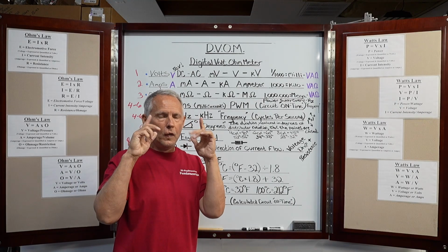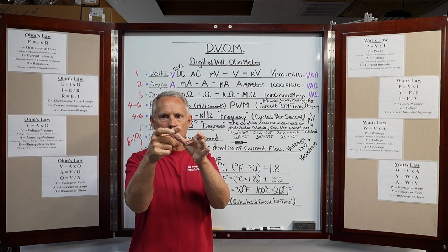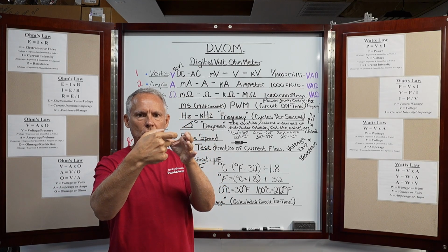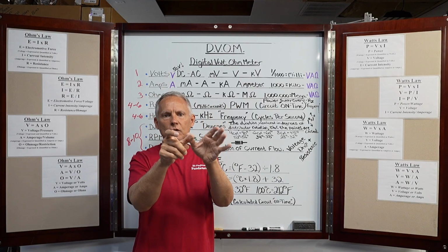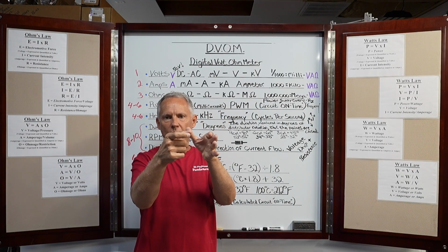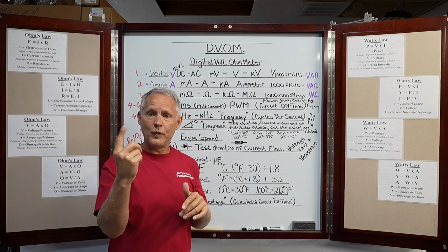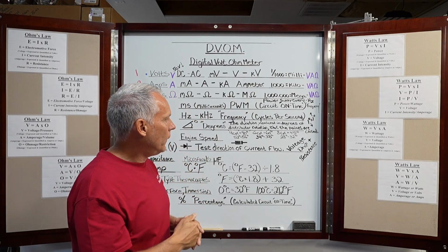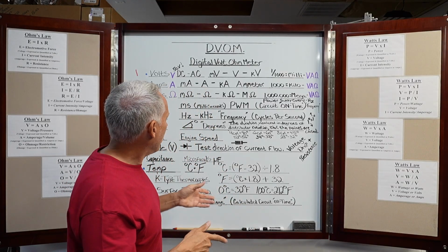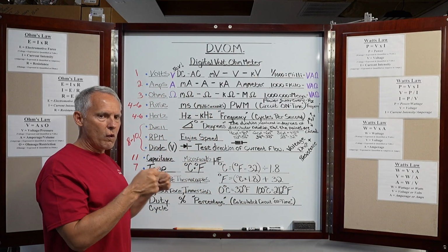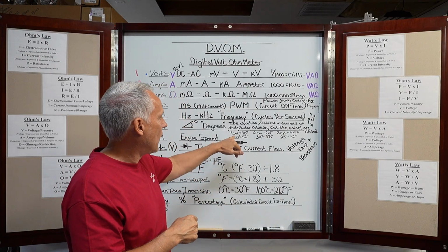So as the distributor rotates 45 degrees, let's say that's cylinder 1. The next 45 degrees, cylinder 2, or 1, 8, depending on the firing order. But let's just say 1, 2, 3, 4. So the first cylinder would be 45 degrees, the next cylinder would be an additional 45 degrees, all the way around 360 degrees until you get back to number 1. Now, on an 8-cylinder, since there's 45 degrees between each lobe, what is dwell? When you're setting dwell on points, what is that?